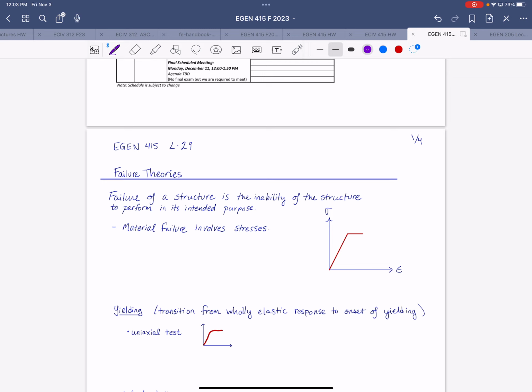You could do the moment at A and then set everything up with respect to the angle or the slope at A, and take the partial derivative with respect to the moment at A. So you could do it that way too. Either way, you'll end up with a result that will allow you to then write all of your reactions in terms of Q and L. Then you want to find the maximum deflection in the beam.